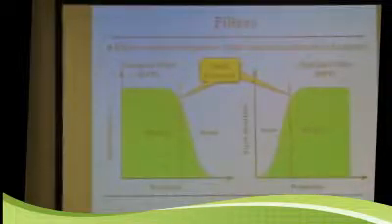They initially did that, remember this was back in the 20s and 30s, because they knew harmonics would occur. People were building their own transmitters, and at the very least, the second harmonic and the fourth harmonic here are essentially within the ham band. So if we were disturbing anybody, we were just disturbing other hams. So that was considered not as important, although it doesn't mean we're supposed to do that. But what we really want to do is not put out anything of any substance on these other frequencies. When we send out the signal at 3.5, we want it to be just 3.5.